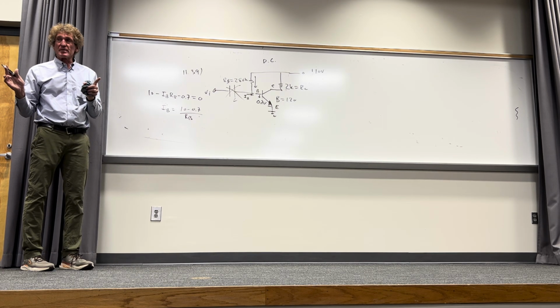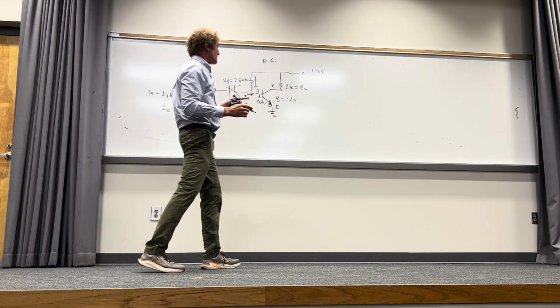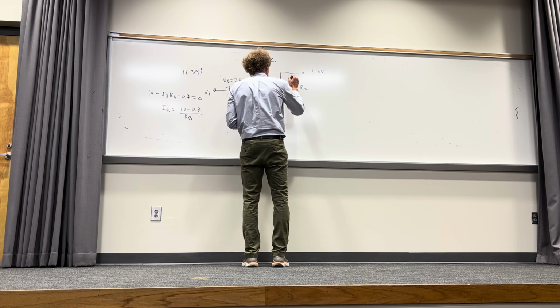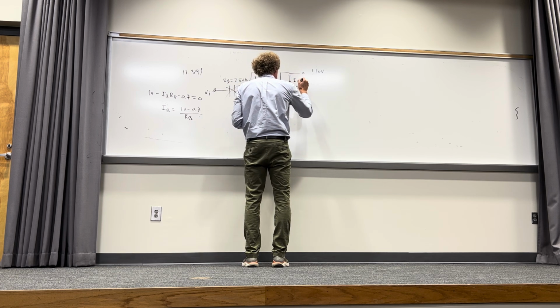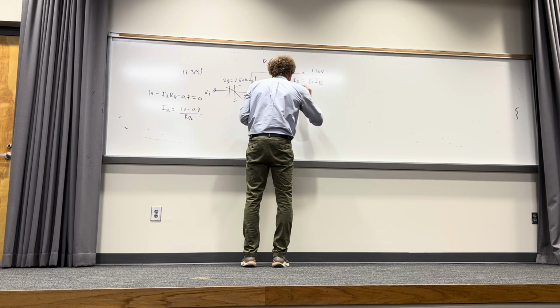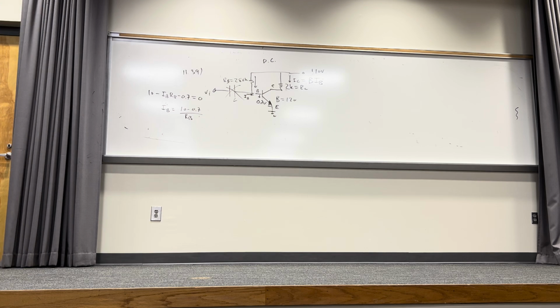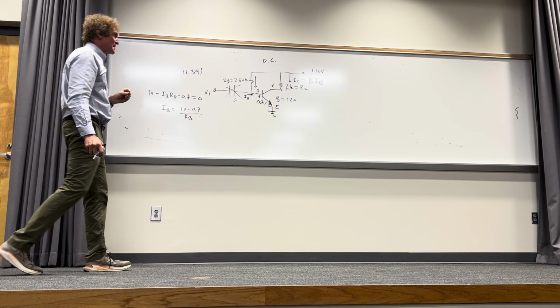It's this straightforward, but just watch, because this stuff you can get lost if you don't keep up. Now if I know that, IC right there is beta times IB. Can everybody follow me on that? Remember, beta is the current gain of the transistor. Beta is 120 in this case. Just a show of hands. You understand the idea? If I have the base current, and this transistor is in what's called the active region, I have IC.